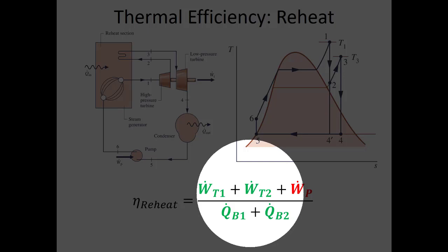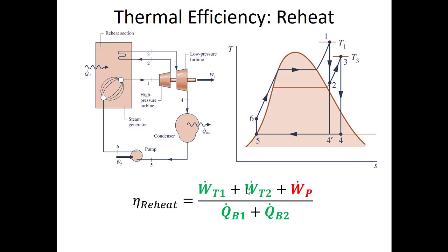Now, I think we mostly avoided making this mistake on the exam, but we've got to be careful of the signs. So my advice, because I think it's less confusing, is to use expressions for W dot like you would derive them from the first law. So that W dot is always going to be m dot times h in minus h out. And I say always, but it's really provided that we can make all those assumptions we're used to making for turbines.